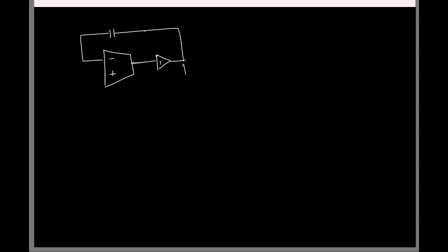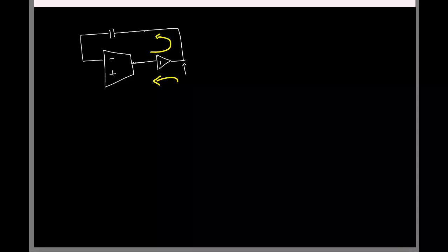Now this buffer will fix this voltage to something, so we'll not have a feed forward. I mean, the other way to think is this buffer is only going to allow signal flow in this direction, right? It will not allow signal in this direction. The current coming from that VCVS cannot flow through the buffer.